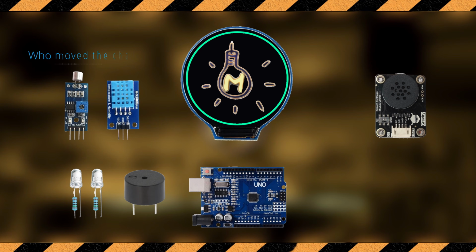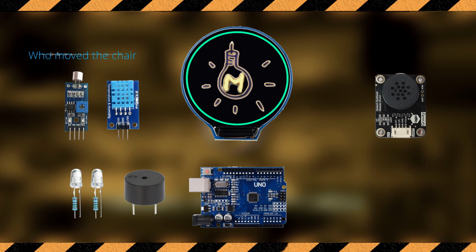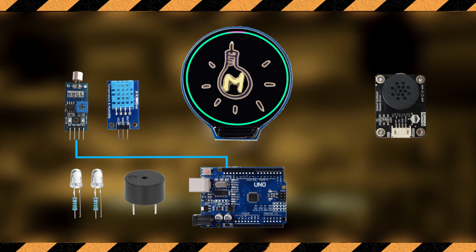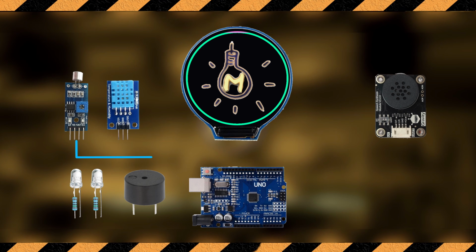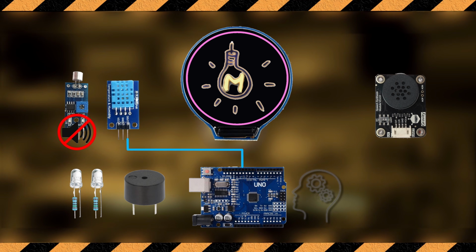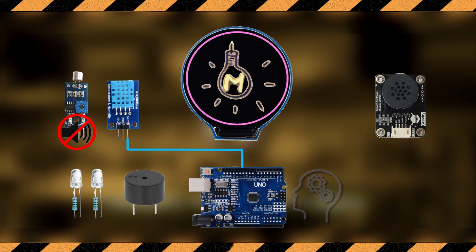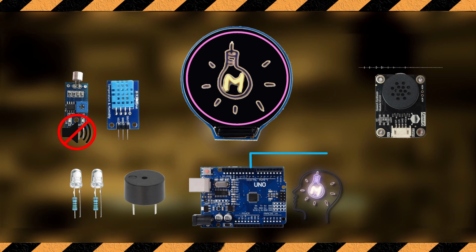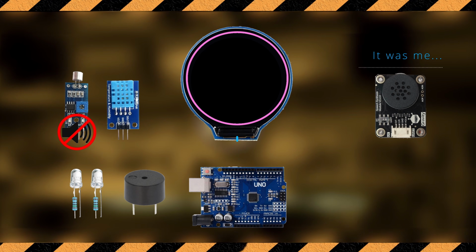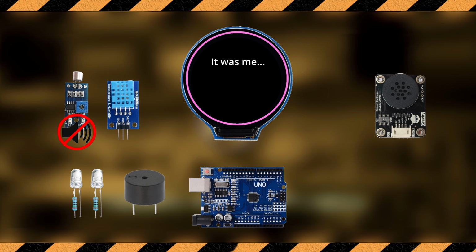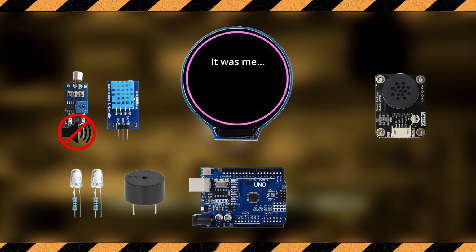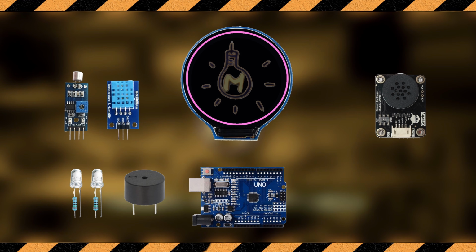Now here is how the basic logic works. The microphone module picks up louder noise such as a human voice and sends a signal to the Arduino. The Arduino receives the signal, mutes the microphone, sets the color of the circle on the display to purple and then asks for temperature and humidity values. It uses them to generate a random value that is tied to a list of words in the code. It then sends out the signal to the speech module to speak out the chosen word while displaying it on the screen. After some seconds, the microphone gets unmuted and is ready to capture another question.